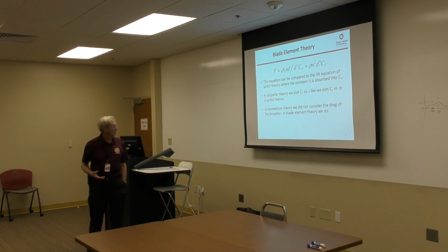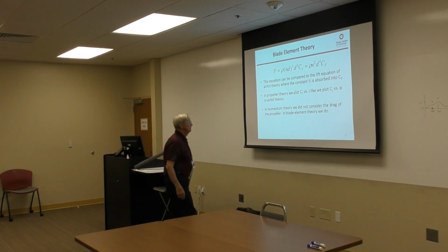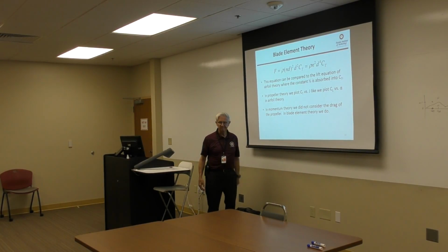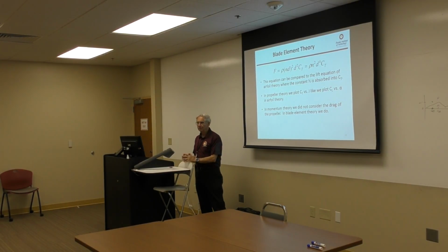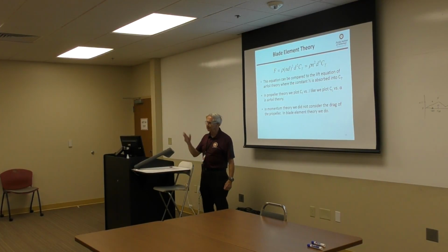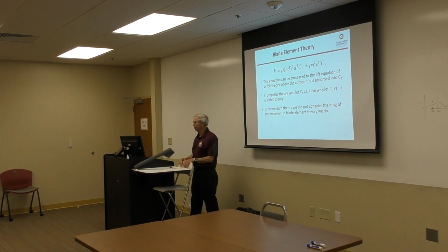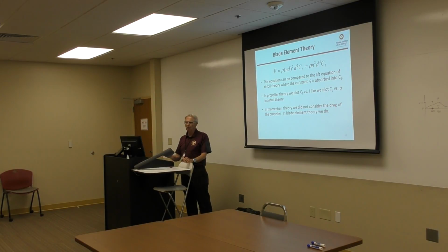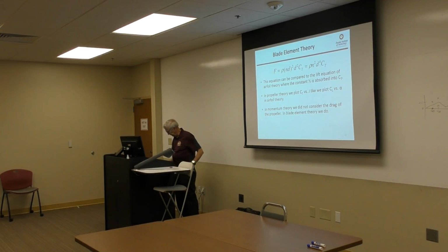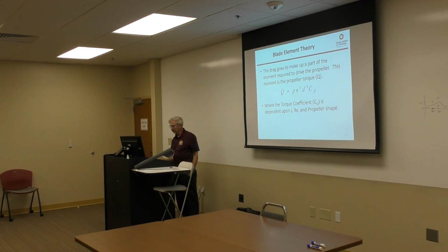Okay, and before, in our simple-minded theory, we didn't consider the drag, right? Remember, that was one of the things we said when we looked at momentum theory, we said, oh, we'll just say that this thing doesn't have any drag. Well, it does have drag. And so in blade element theory, we do consider that. And here it is.